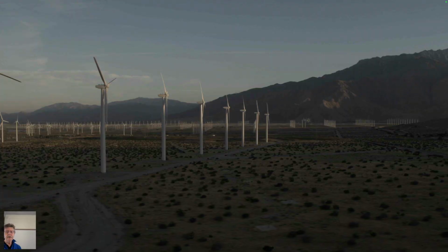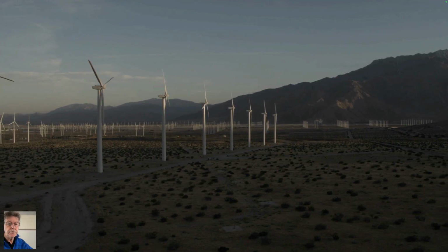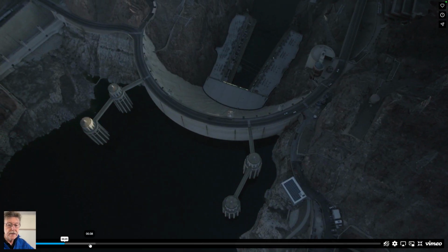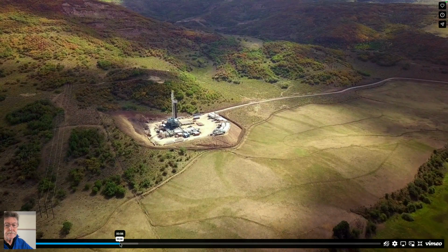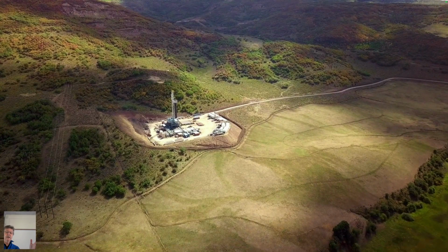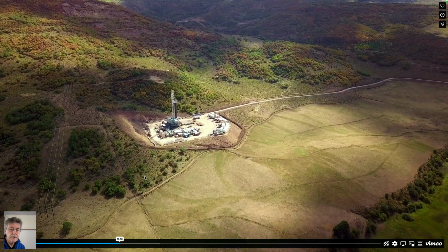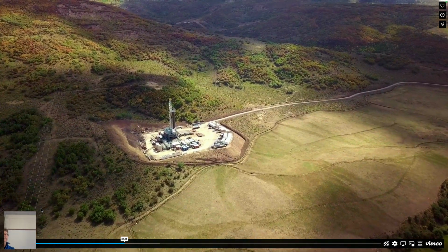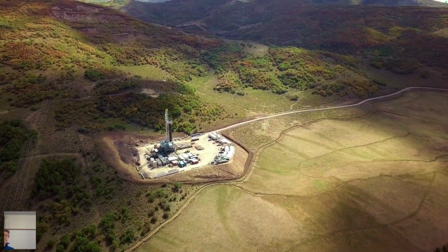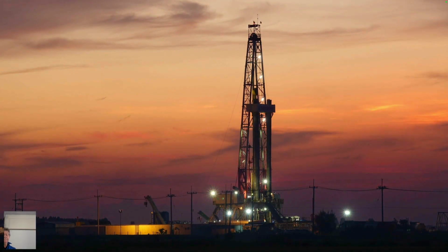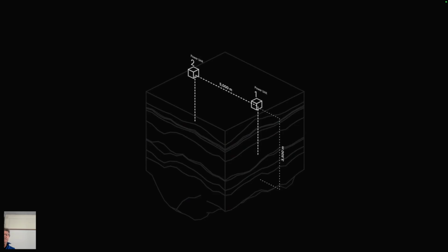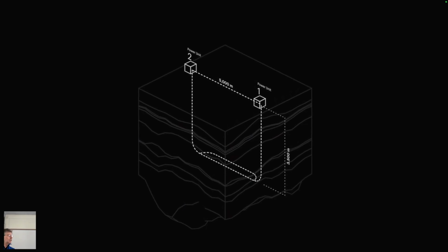EVOR, it's for a company that uses geothermal recovery by conduction, not by convection. So their whole mechanism is to drill down to where the heat is. So you have to drill down to 3 kilometers if you want to get temperatures of the order of 100 degrees centigrade. And they're going to show you that. And then once they get down to that depth, they build themselves a geological heat exchanger. And so that has water advecting through it, but not through the rocks. It's going just through the borehole.